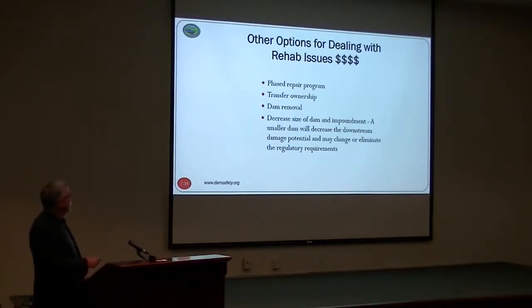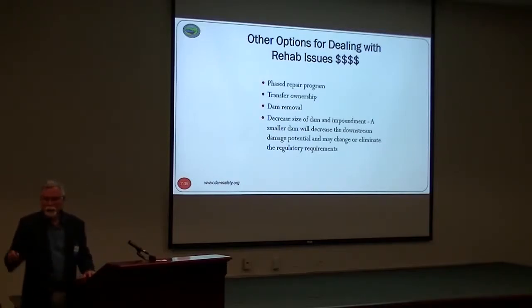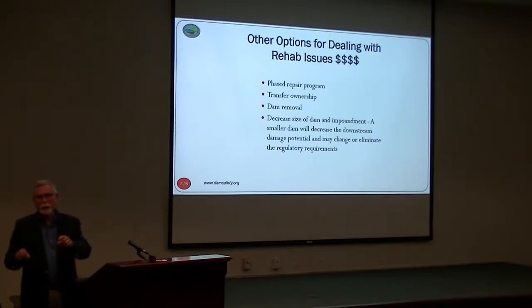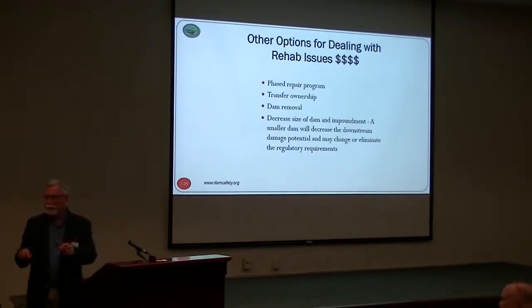So that's a good option. I know here in South Carolina, it still cannot be a high hazard dam regardless of its size, right, Jill? That's not a factor in hazard classification. It isn't how much water is released. That's right. But if somebody had a 24-foot high dam, 40 acre feet, but there was still a house below it, it would still be a high hazard.